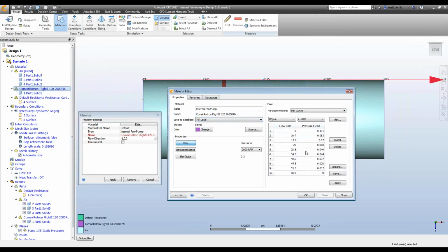All right, so 0.05. All right, so we're going to be between points 4 and 5 on the fan curve, and like we said, that's 0.05 inches of water, so that works out well. We had about 25 cubic feet per minute, which falls in between these 2 points. So everything is working like it should, which is great news.